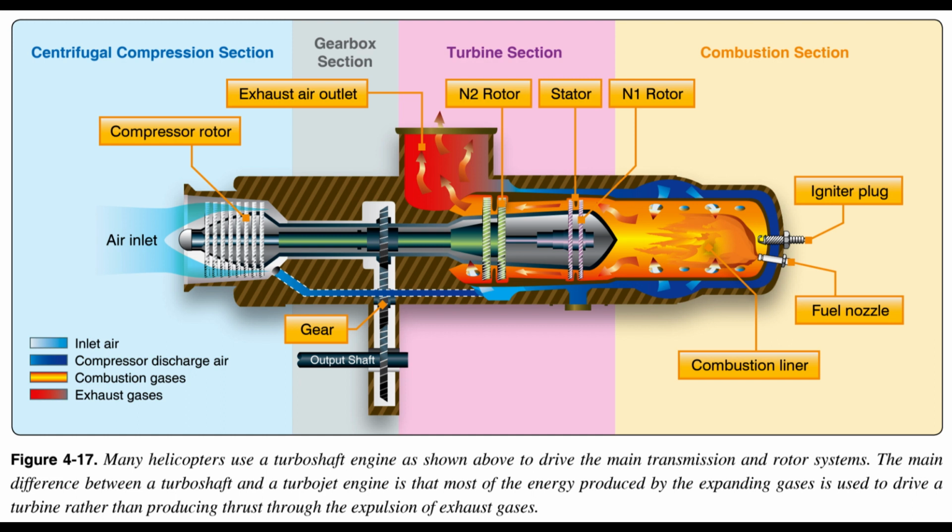The freewheeling unit or autorotative clutch allows the main rotor transmission to drive the tail rotor drive shaft during autorotation. In some helicopter designs, such as the Bell BH-206, the freewheeling unit is located in the accessory gearbox. Because it is part of the transmission system, the transmission lubricates it to ensure free rotation. Helicopter transmissions are normally lubricated and cooled with their own oil supply.